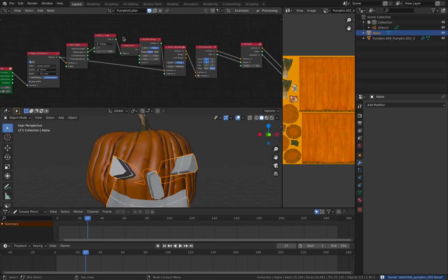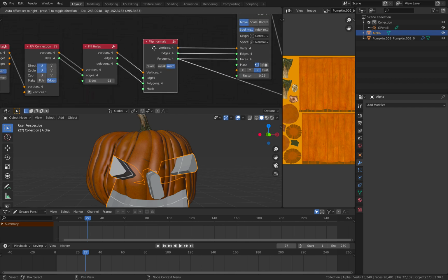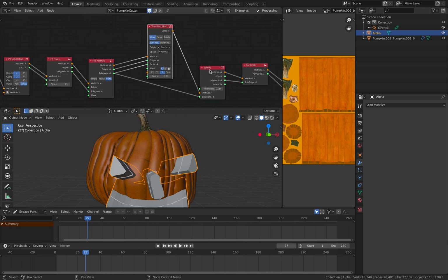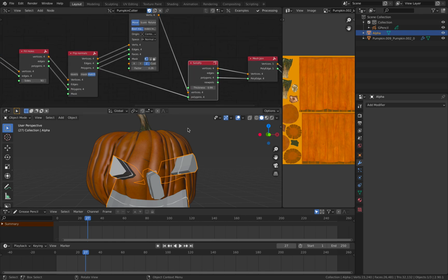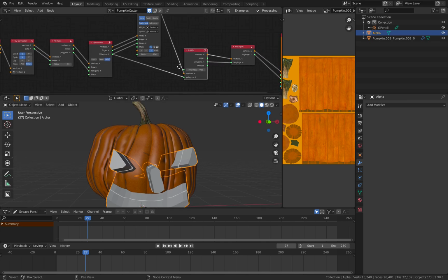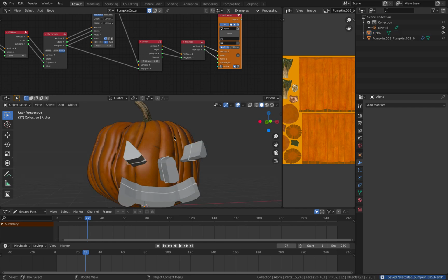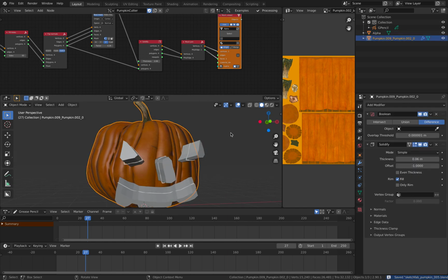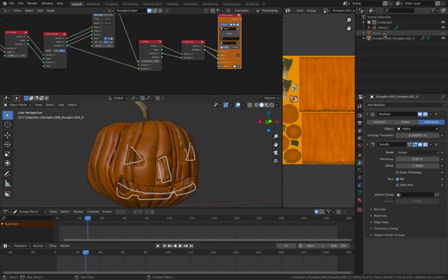So this whole thing is just simply resampling the grease pencil strokes, etc. And then I fill the holes, flip the normals, etc. Transform mesh and solidify. This transform mesh and solidify work together. Maybe we need to change some of the parameters, but in this case I'm just gonna leave it like that. So what's gonna happen next, after you make your cutter design, is simply use boolean to make a cut. Now I can hide this alpha, like intermediate mesh.